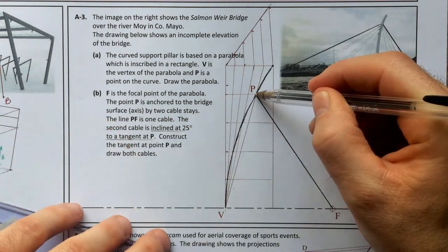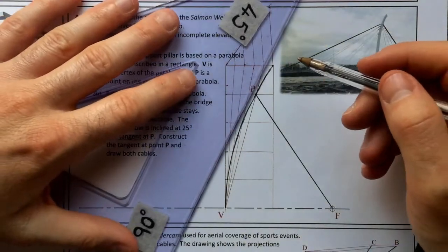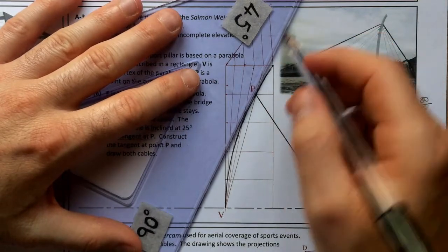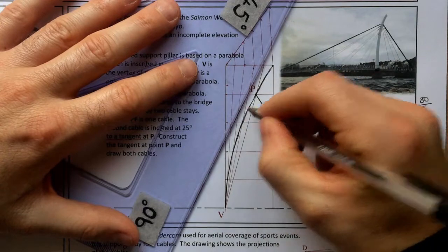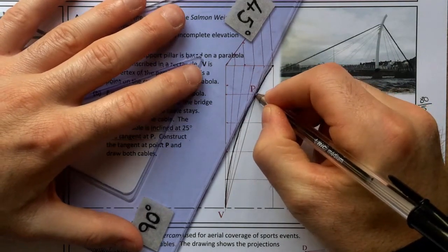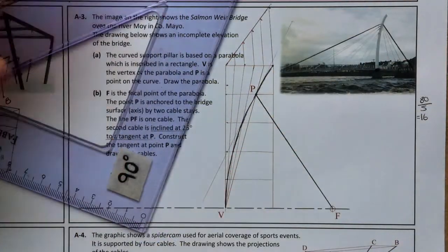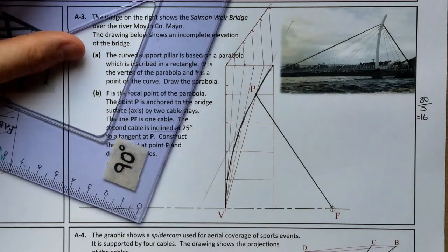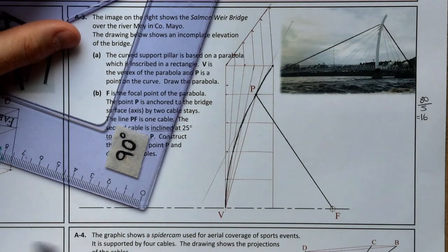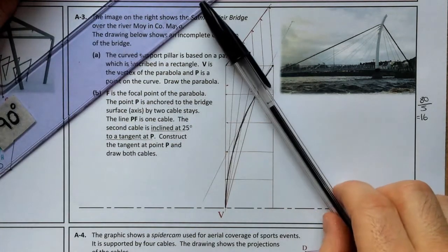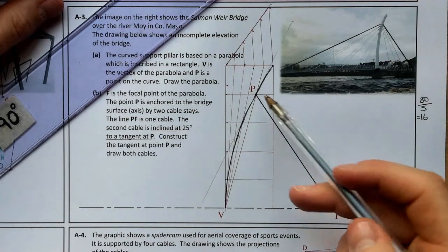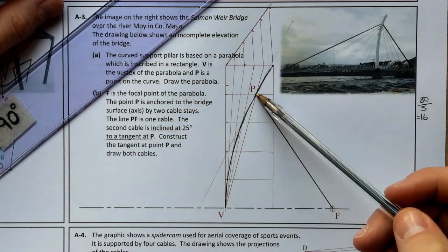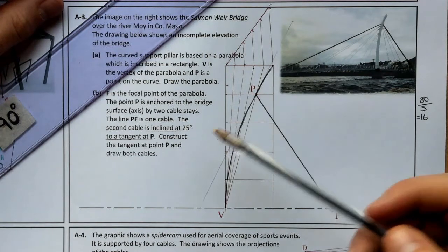So to be able to get a tangent, our tangent, we'd imagine, is going to look something like that. Okay, it's going to go off and it's going to connect depending on how well I drew my curve, but our tangent is going to look something like that, I would imagine. Okay, and to be able to get the tangent, if you think back to during start drawing, anytime you had a tangent to an ellipse or something like that, you connect up the focal point to the point, and what you actually do is you bisect the angle between the 2 focal points.